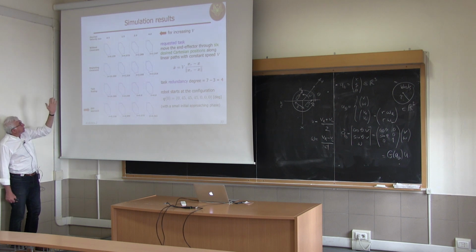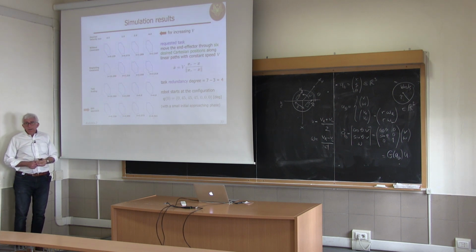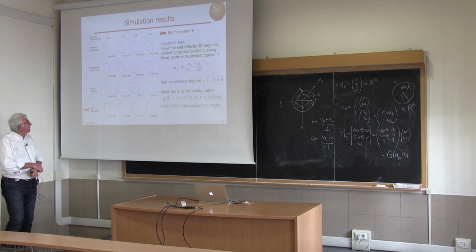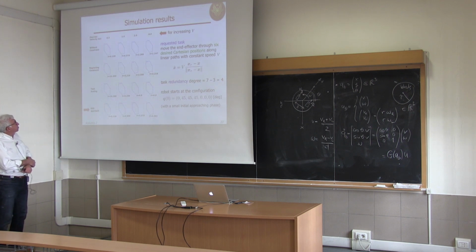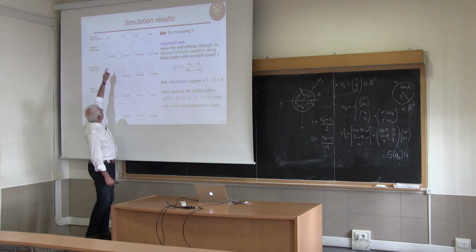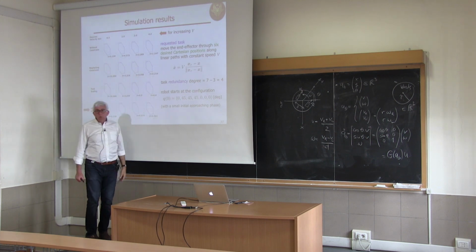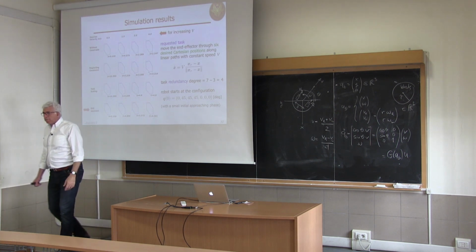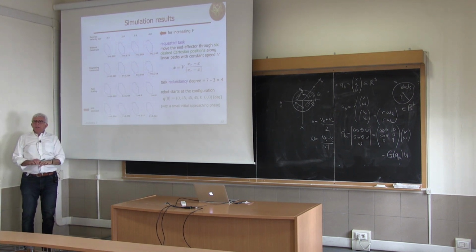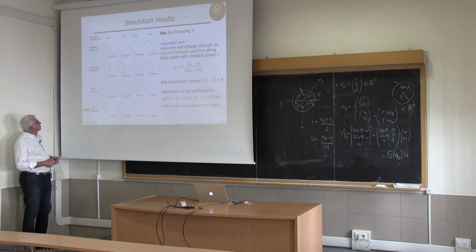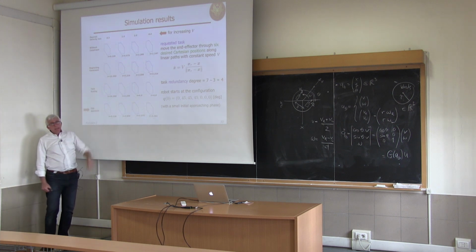So you see that you execute perfectly the hexagon, because once you are on it, there's no limit, you're not saturating any constraint, you have no limits for the joint ranges as well in this simulation. And the only thing that changes is the total time of one cycle: about 9 seconds, 4.5, 2.2, 1.1 seconds when you're going very fast. So this is kind of a ground truth or benchmark. This is the best you could do without constraints.